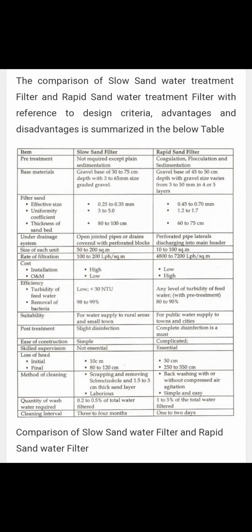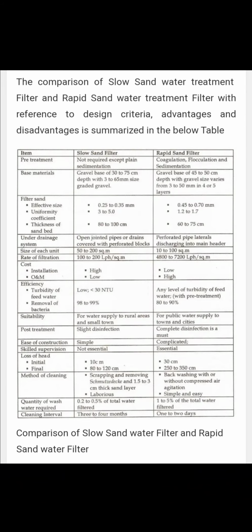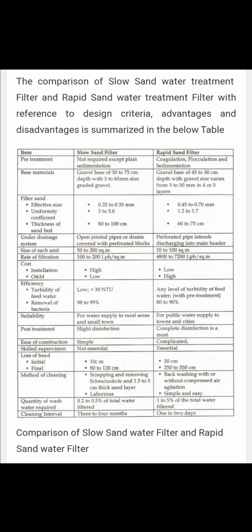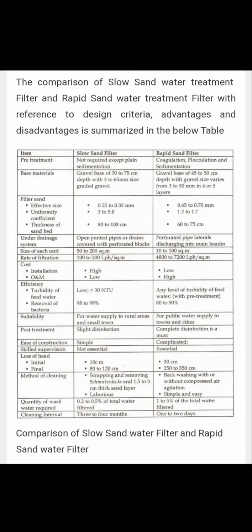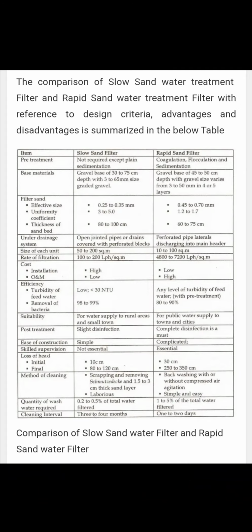So these are the various advantages of filtration, so filtration is a very important process in water treatment. Now you can define what filtration is. Filtration is nothing but allowing water to pass over a granular filter bed, and that bed is nothing but sand. Water is allowed to pass through the bed of sand, and that is the process of filtration. During this filtration process, whatever impurities are present in water are removed. It may be color, odor, suspended impurities, colloidal impurities, bacteria. All types of impurities present in water are removed during the process of filtration.